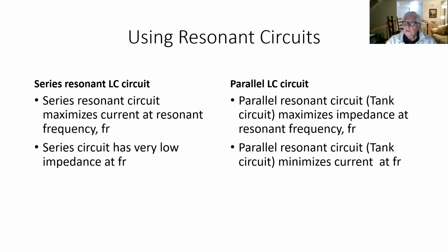It allows us to choose a very specific frequency to pick up a signal at that frequency. In a series resonant circuit, we maximize current at that resonant frequency, but we have a very low impedance, basically 0, essentially no resistance.